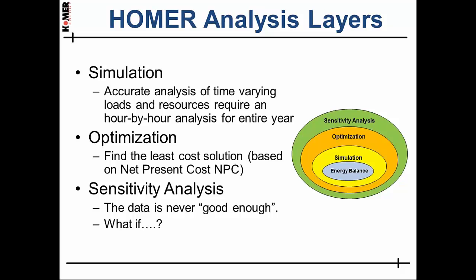So the HOMER software enables you to gain these insights by its approach to modeling. HOMER Pro uses an approach that combines simulation, optimization, and sensitivity analysis. Simulation in HOMER Pro uses, by default, an hour-by-hour energy balance to dispatch the components in a HOMER model to ensure that there is adequate energy supply available to meet the load at all times.